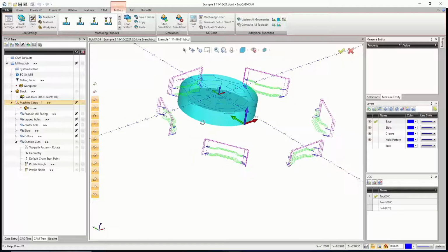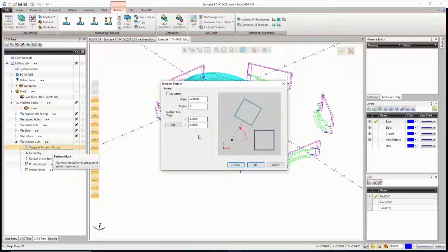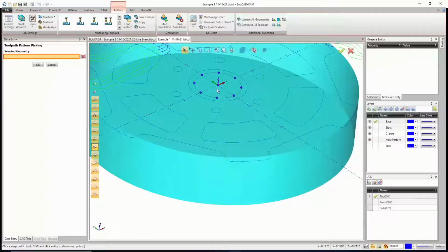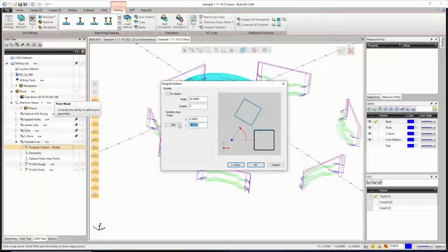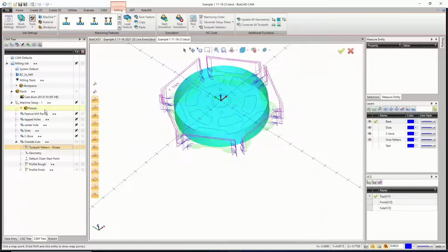The adjustment we have to make is on the toolpath pattern. When we're on here, mine is going off the origin of the part, and the origin for my part is the center of the part, so it's XYZ0. Yours, what we're going to do is just hover over this arc in the middle, then pick that center point. And what you'll see the difference is you have a Y that shifts your rotation center point up 3 inches to the center of the part. And then if I hit OK, it fixes it all. So that was the only difference, and which is totally fine.